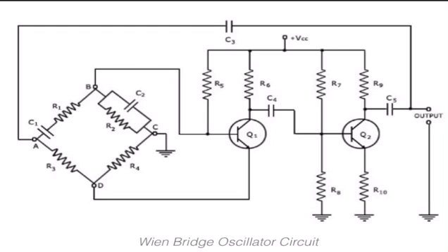So it is a two-stage amplifier with an RC bridge circuit, and the circuit has lead-lag networks. The lag phase shift increases with frequency, and the lead decreases with frequency. In addition, by adding the Wien bridge oscillator at a particular frequency, it becomes sensitive. At this frequency, the Wien bridge is balanced with a phase shift of zero degrees.